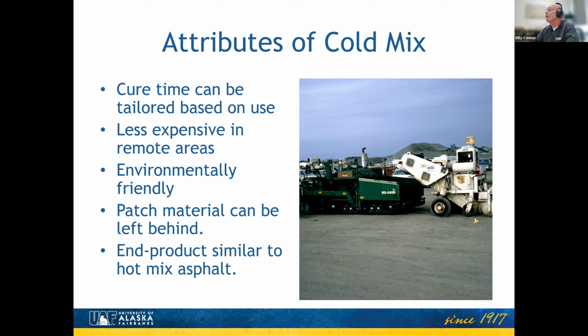The nice thing about it is we're looking at possibly, for remote areas, reducing the cost of actually paving by 50%, because we don't have to bring in a hot mix plant and all of the fuel oil to heat that and all that goes with that. So we're reducing the cost by that, and that's almost 50% of the cost of the equipment that's going in there. It's environmentally friendly. We're not getting the volatiles coming off that we would get off a hot mix. We're not getting the fuel oil burning as a result of that coming off.